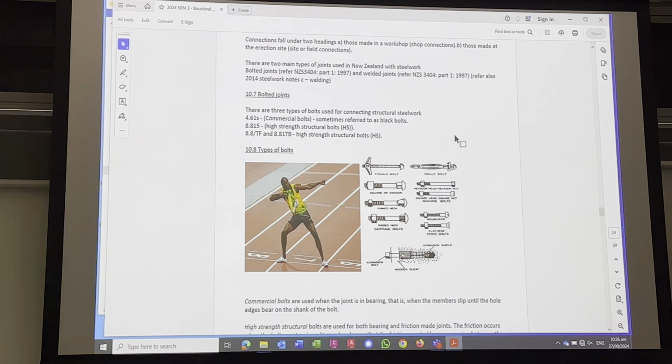But then you tighten it up. That's the only trouble: it's very hard to tighten up when it's a slotted hole, because there's more slop in it. So you're a little bit vulnerable to sideways movement. But generally speaking, they do use that when you're going into concrete.